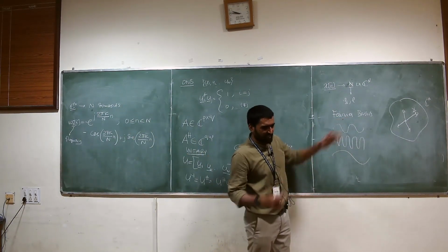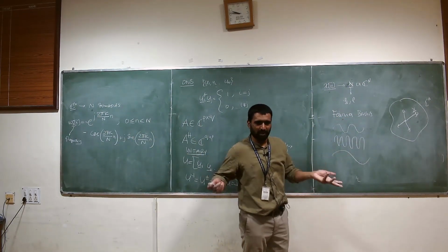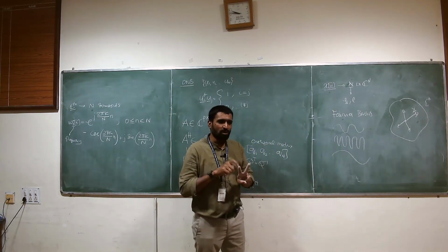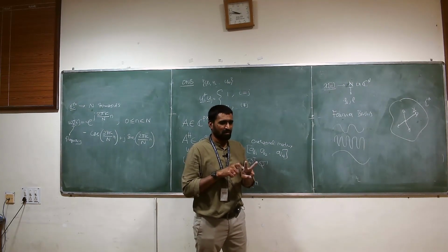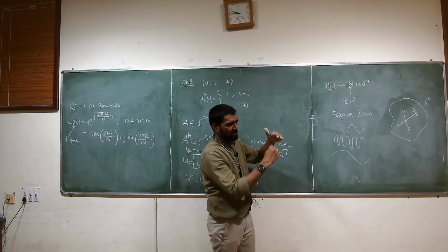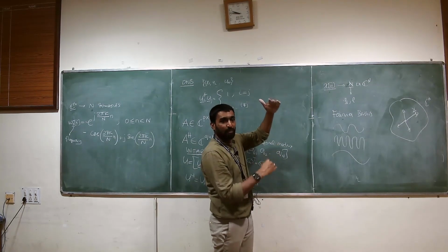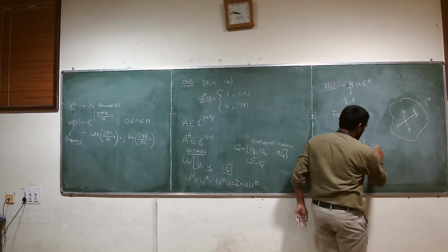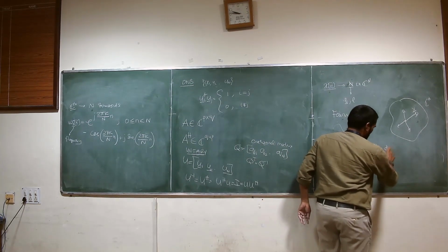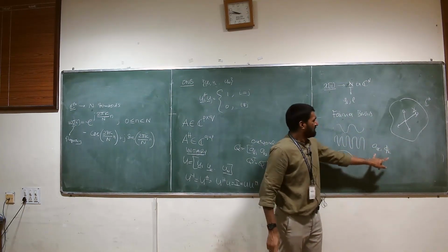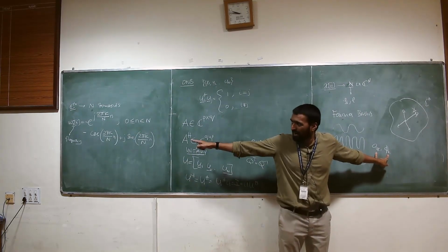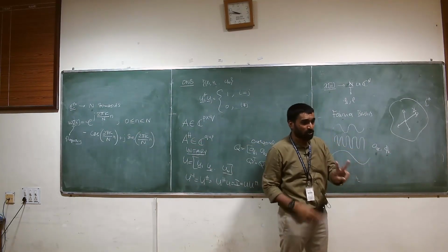Fourier analysis, decomposing a signal into sinusoidal components of different frequencies, you always have to choose two numbers for each sinusoid. What are the two numbers? You have to choose, for any frequency, how big the amplitude of my signal is, and what the phase of my signal is. That means you have two numbers that you have to choose, a_k and phi_k. These two numbers are essentially compactly represented by a complex number, because a complex number has two real numbers.